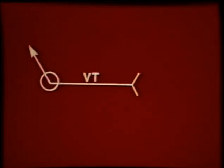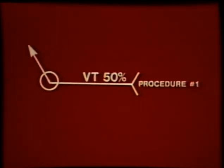When a test is to be applied on a specific section of weld, the section length is placed to the right of the symbol. If less than 100% of the length is to be inspected, this can also be specified by a percentage. In both cases, the required areas are usually specified in the written procedure.